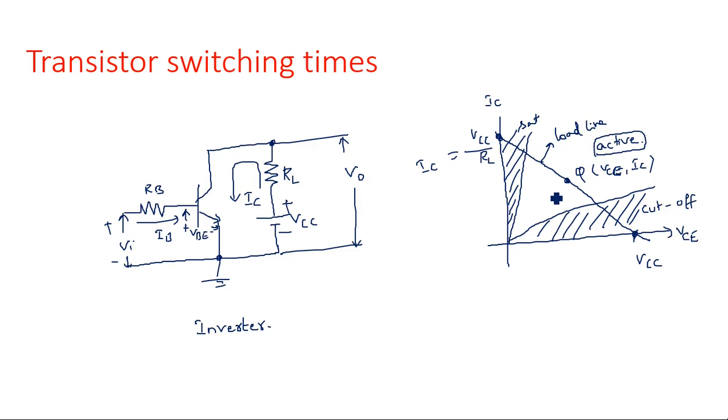Okay, now what I am going to explain in this transistor switching times is, suppose assume transistor T1 initially is in off state. Listen clearly. Initially T1 is said to be in off state. Now I am giving sufficient input voltage, like VBE is equal to, let it be 1 volt. Minimum required potential is 0.6 or 0.7 depending upon the type of the material, silicon or germanium.